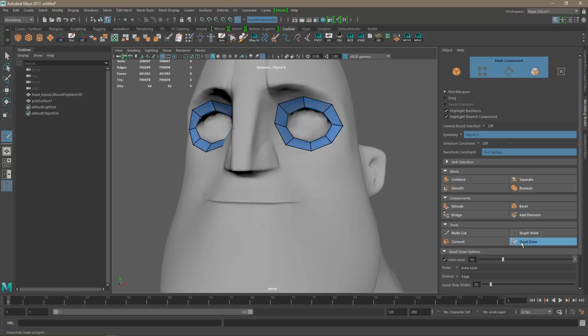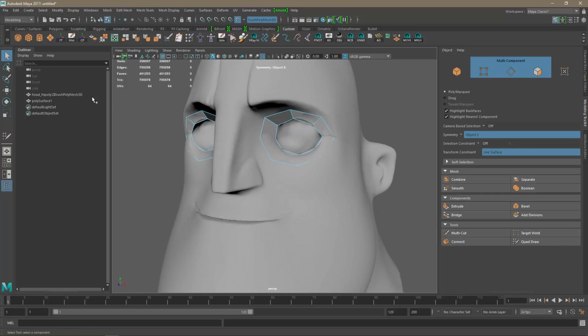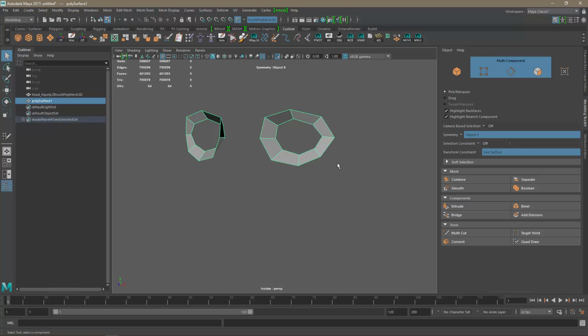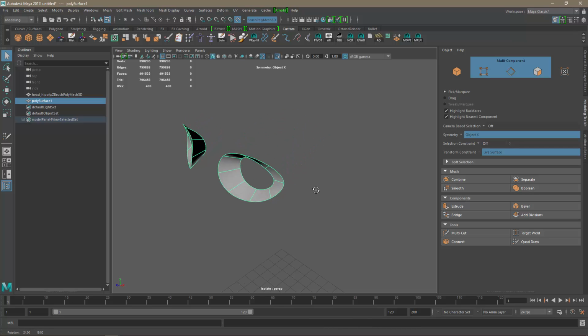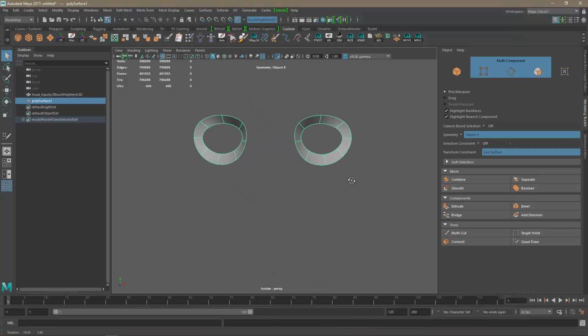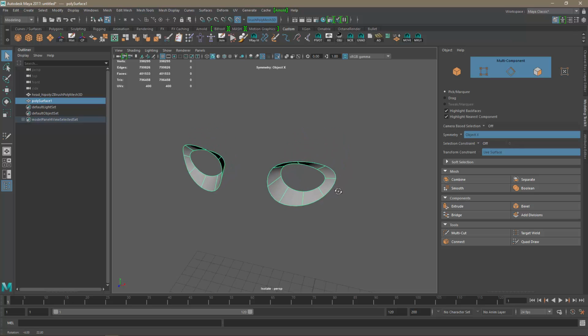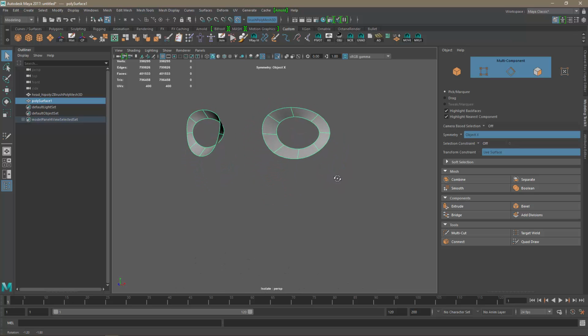I can actually show you a preview right now. If I select my mesh and isolate it, this is the mesh that I generated. If I press the key 3 on my keyboard, this is how it looks. This is a smooth preview. It's not actually changing the mesh, it's just previewing how the mesh will look once it's subdivided. So as you can see, it will become very smooth.